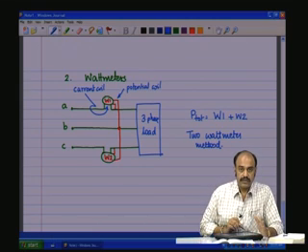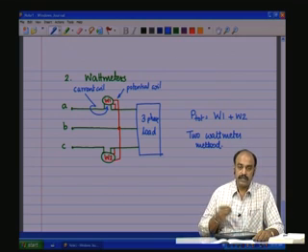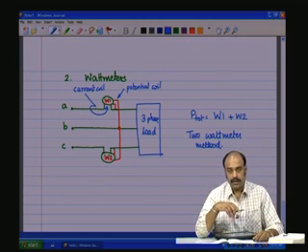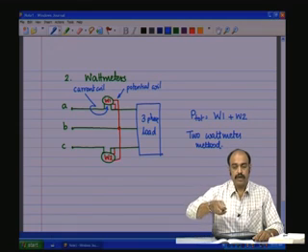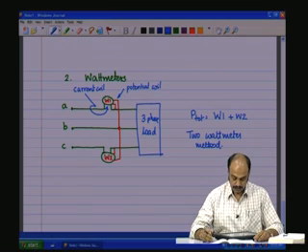So, if there is a center 0 wattmeter, then you can take the readings easily. Otherwise, if it is only a one-direction wattmeter, you will have to reverse the direction if it goes negative, when the power factor is pretty low.